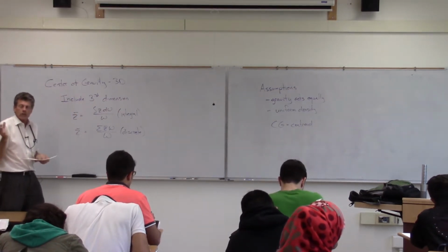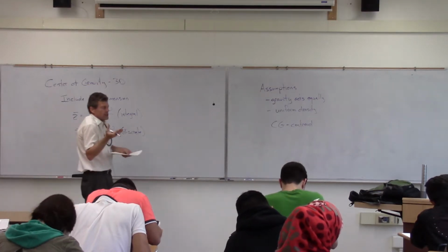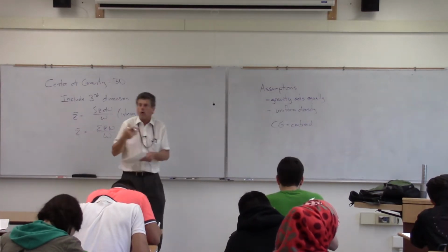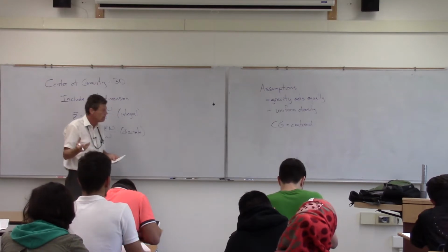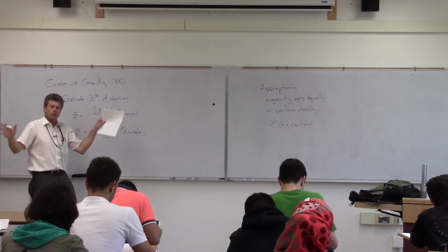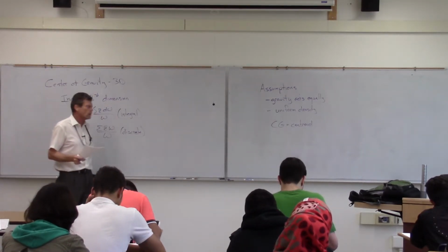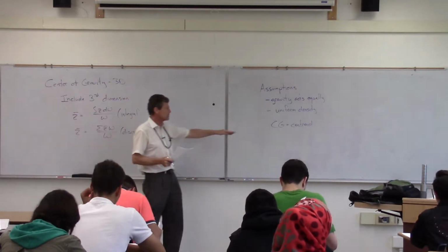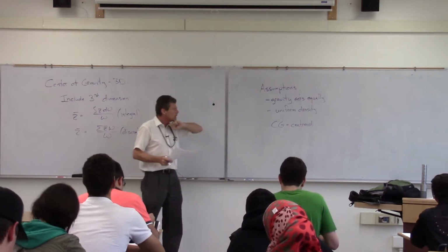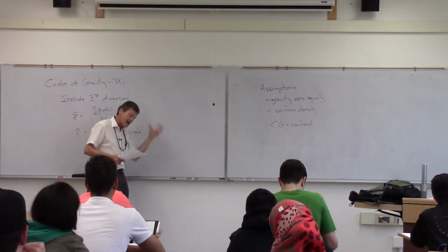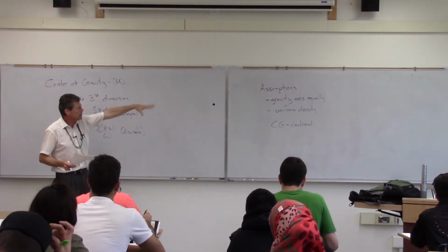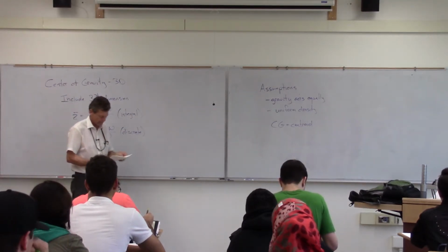And the nice thing about the centroid is that we're finding the centroid of a line or an area or a volume, and it doesn't have anything to do with material properties. We don't have to go look up whether it's steel or concrete or anything. The center of gravity will be acting at the centroid if it meets those two assumptions.